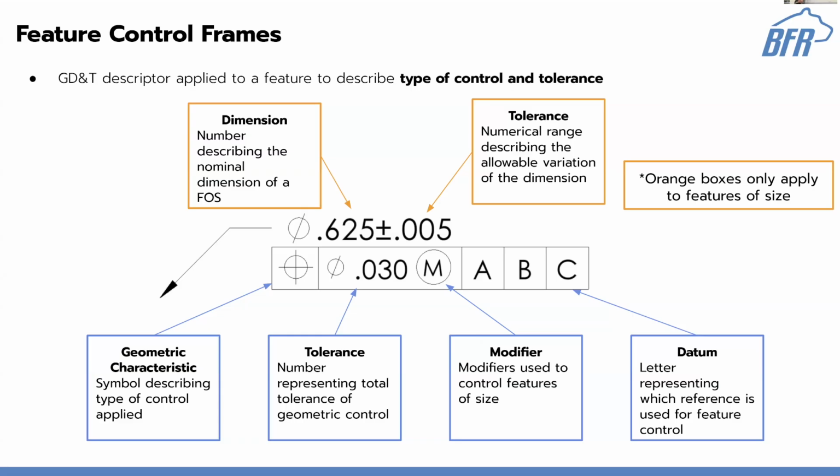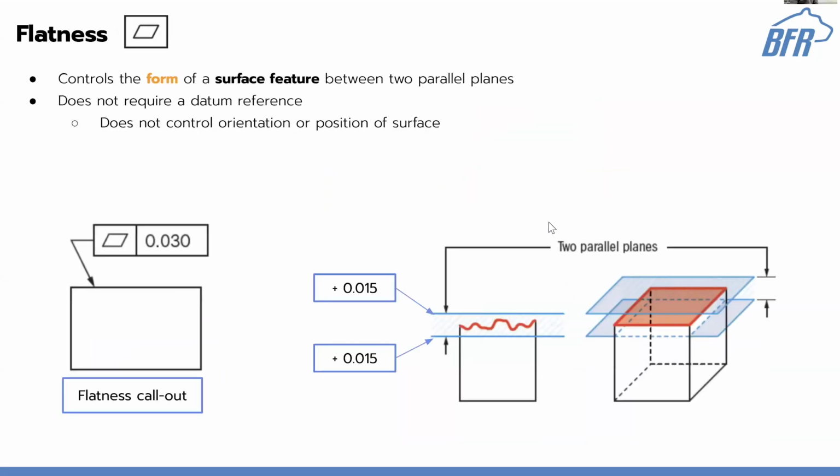You'll see some examples later of flatness being used. Oftentimes it's just one datum, where I only need to constrain it like this, and I'll measure across whether or not it's moving around or rotating. It doesn't really matter. So you can have less than three datums if you want. It gets really funky if you're using stuff like true position. You can do a lot of cool stuff with using fewer datums to give yourself more room for certain things. But that's for another talk.